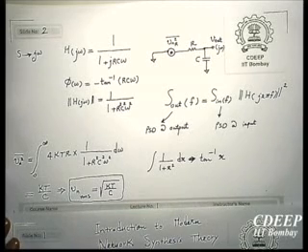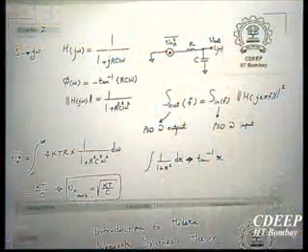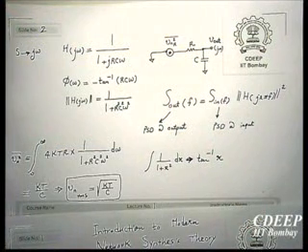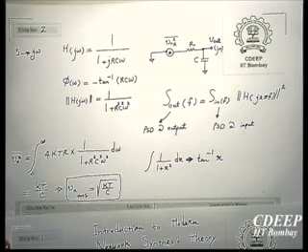So therefore, you cannot apply any signal. The signal you apply should be at least 10 times above this RMS value. In other words, RMS value of the signal at the input should be 10 times of this RMS value. And this RMS square is inversely proportional to C. That's why using larger capacitors leads to less noise. That is very important. For example, in sampled data systems, you may need to use larger capacitors exactly for the same reason.